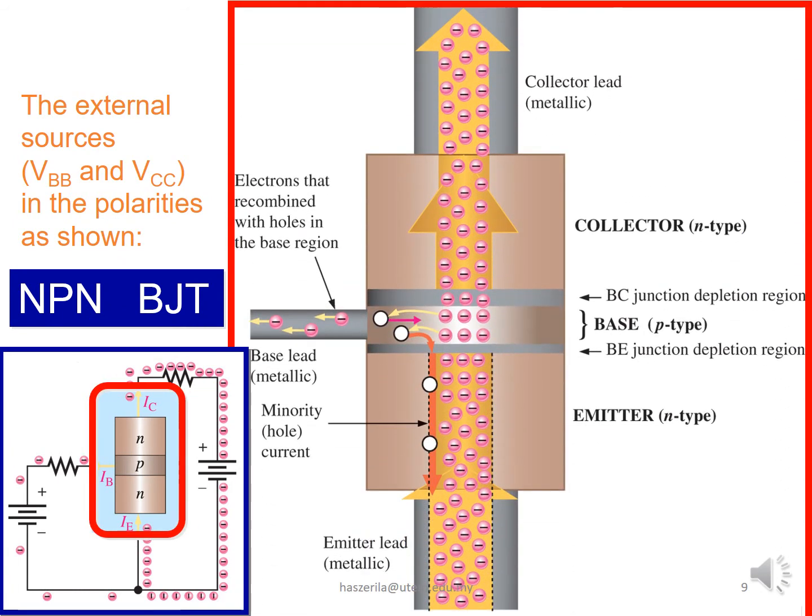The NPN transistor is designed to pass electrons from the emitter to the collector, so the conventional current flows from collector to the emitter. The emitter emits the electrons into the base, which controls the number of electrons the emitter emits. Most of the electrons emitted are collected by the collector, which sends them along to the next part of the circuit.